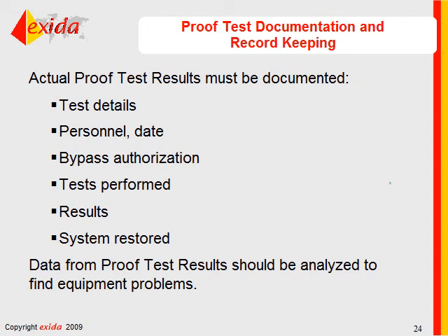If we look at performing a proof test where you do a full stroke in combination with the leak test, then typical FMEDA results suggest that you can get up to like 90% proof test coverage. So let's say full stroke just 75%, full stroke plus leak test 90%.